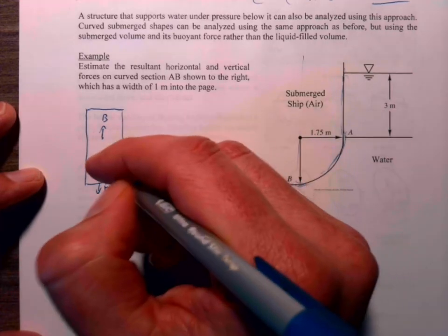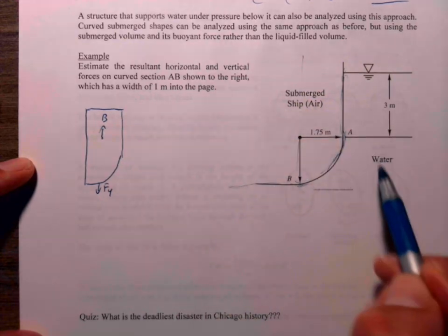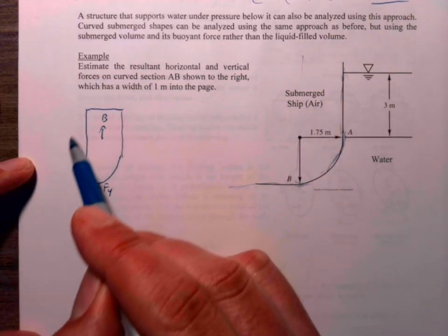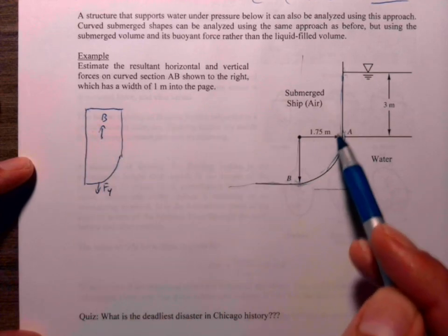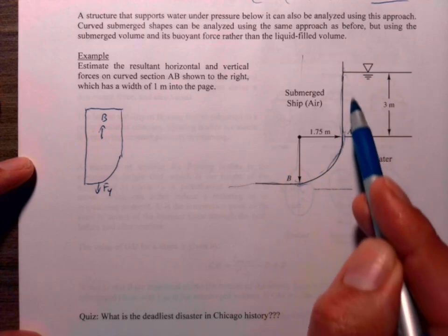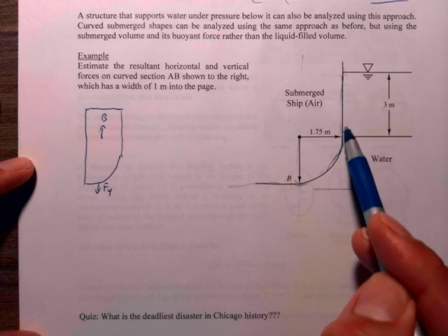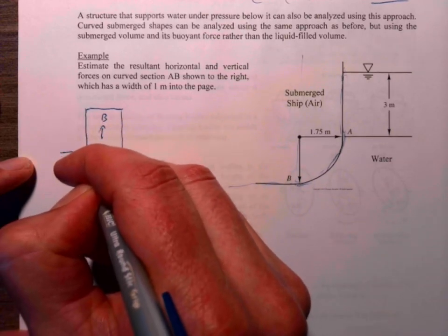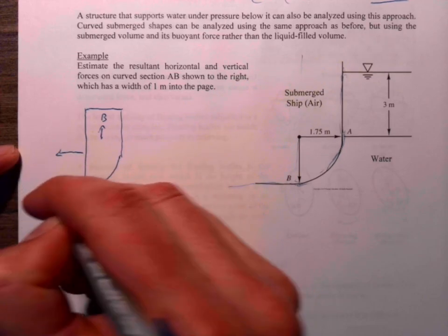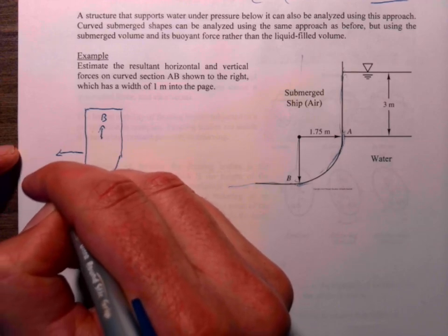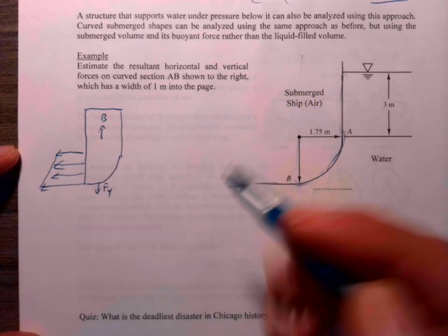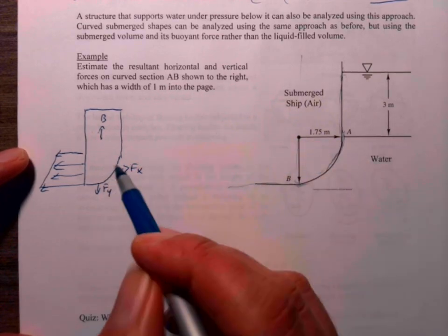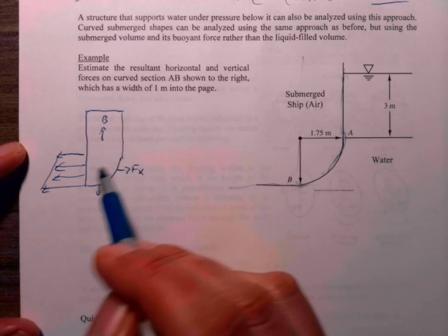And then there's going to be pressure here from the fluid that's pushing on that one. Again, if it went all the way to the surface, there'd be pressure over there. But this part at the top above point A is actually going to be balanced by a force on the structure above point A. So the only part that we need to think about for AB is the part down here. So we will draw it like this. There's this force there, and it gets bigger. It would intersect with zero. So there's kind of a distributed load here acting this way from the water pushing on it. And then likewise we're going to have a force in the x direction here on the structure that will counterbalance that pressure.